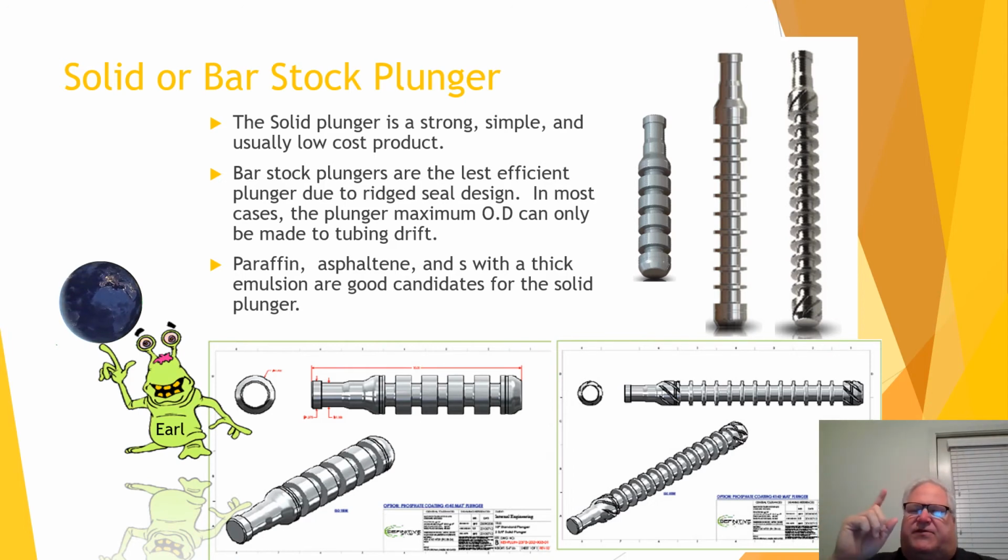What they're really useful for is if you've got a well with a bit of deviation. You'll find that a lot of times a nice straight plunger like this starts to wear on one side. How that happens is these plungers are not balanced, right? So you'll always have one side of the plunger that's a little heavier than the other. As the plunger starts to fall and lay on its side, the heaviest side rolls over and starts to create a wear face on that downward side.